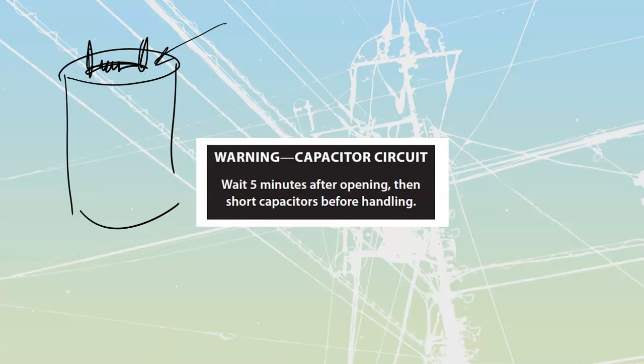So don't do that. Treat the caps with a little bit of respect and give them time to discharge before you touch them, and make sure you're operating them at the correct voltage and the correct frequency.